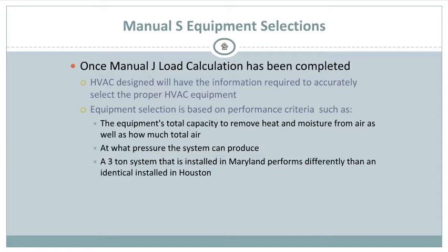One of the things you need to take into consideration when you're looking at these units: sometimes a single-stage unit runs in half tons. So if you've got a 1.5 ton unit, it's probably just a single speed. If you have a 2 ton, 3 ton, 1 ton, those kinds of tonnage, you're going to have a 2-speed switch.